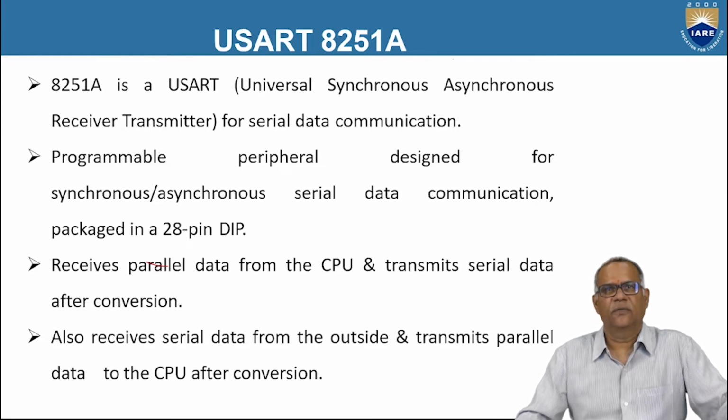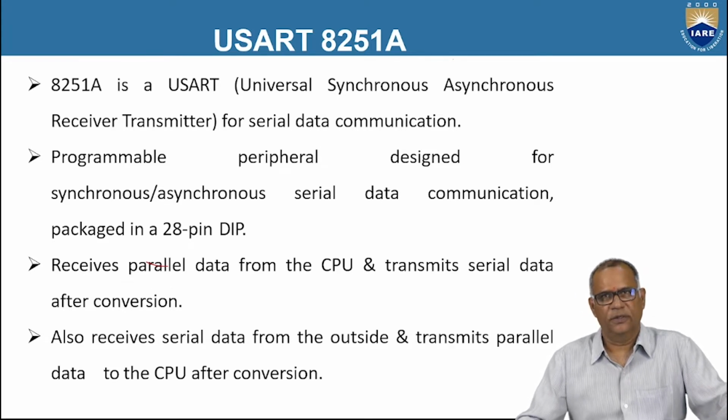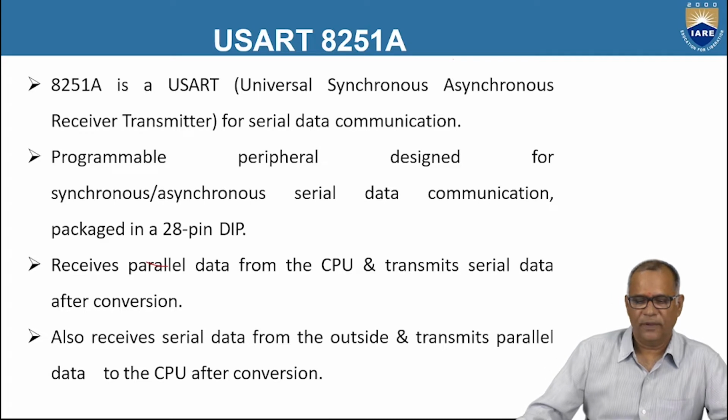Contrary to this, we have full duplex communication where the communication can take place between the 2 points simultaneously. So that is the full duplex communication. So 8251A supports full duplex communication. It is a programmable peripheral interface which is designed for synchronous or asynchronous serial communication.